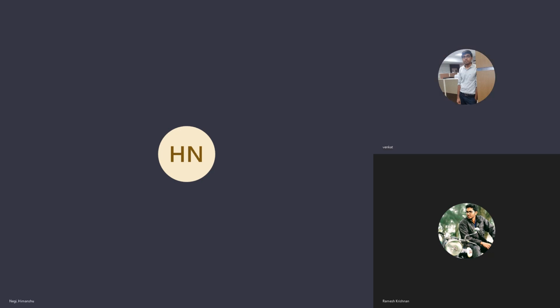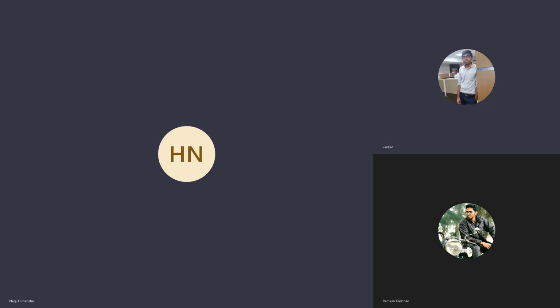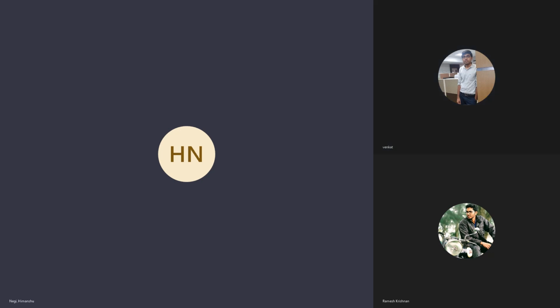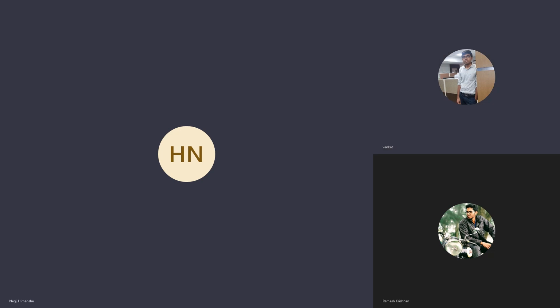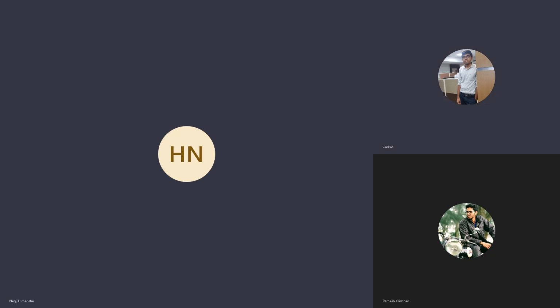Yes, I got it. That's what I wanted to know from my research point of view, for when I do this work. I wanted to know what happens if I bond the surge arrestor to the mat. Based on my earthing calculation, it will favor both lightning and switching.